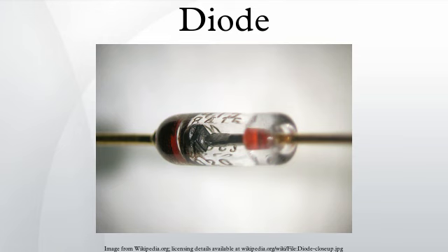The thermal voltage Vt is approximately 25.85 mV at 300 kelvins, a temperature close to room temperature commonly used in device simulation software. At any temperature it is a known constant defined by kT/q, where k is the Boltzmann constant, T is the absolute temperature of the p-n junction, and q is the magnitude of charge of an electron. The reverse saturation current is not constant for a given device, but varies with temperature. Usually more significantly than Vt, so that Vd typically decreases as T increases.